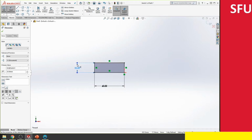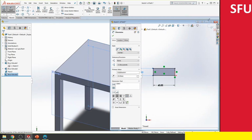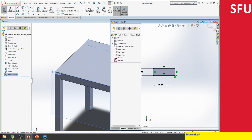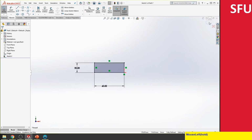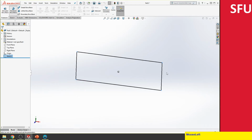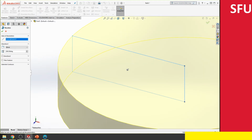Once we have that, now we can actually rotate it about a particular axis. So I can say close the sketch, and then we click and rotate it about a particular axis. Here it's giving everything that you would need. It says what axis do you want to select. So I can select this point inside and then create, and then I can do it by 360 degrees.